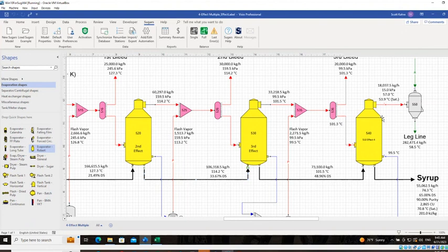So the results you get out of Sugars, if you're back calculating an existing heat transfer coefficient, are probably more accurate than you would get from mechanical design calculations, because it's very difficult to account for things like fouling or pluggages or any mechanical issues that might be happening in the vessel.